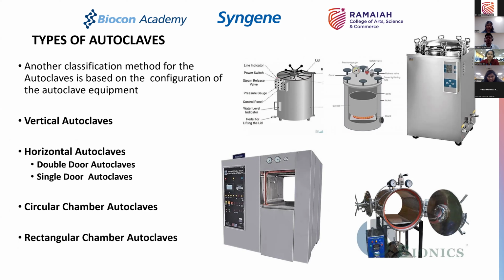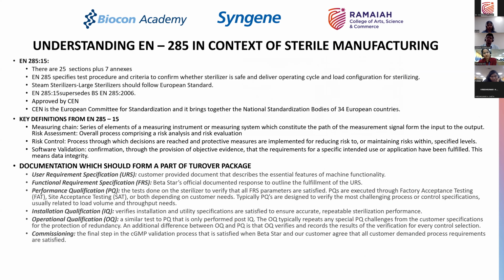So very important that while both configurations, circular and rectangular, are still used in the industry, rectangular today is a preferred configuration in modern day sterile manufacturing operations, because it gives you the capability to maximize the load within a given volume as compared to a circular chamber. However, it is important to make sure that the equipment is properly qualified, and that is where the standards come in, that is where EN 285 comes into the picture, and that is my next topic which I'm going to bring in.